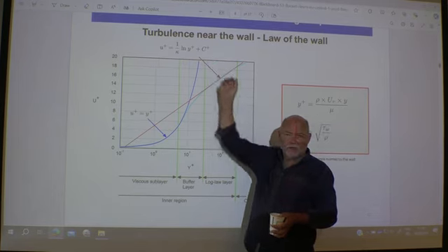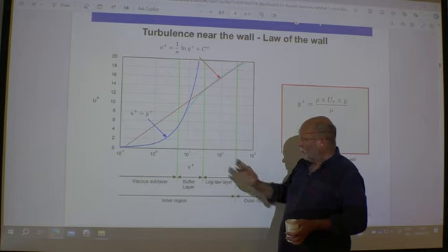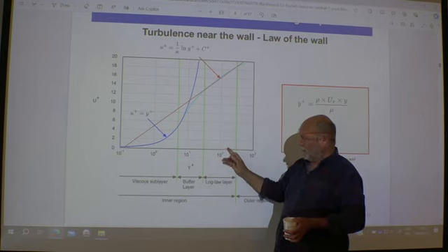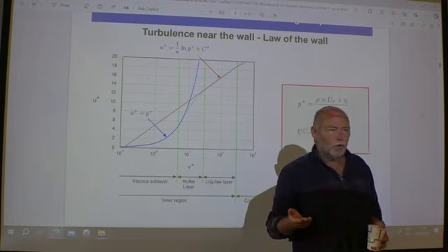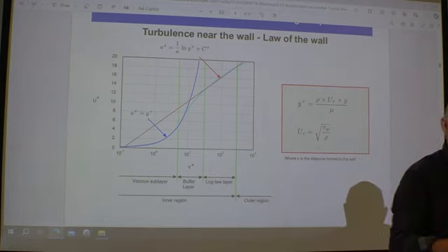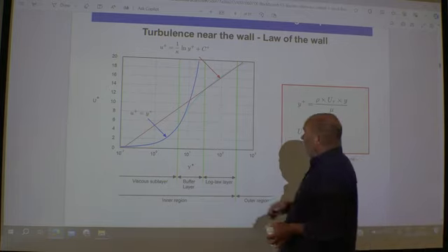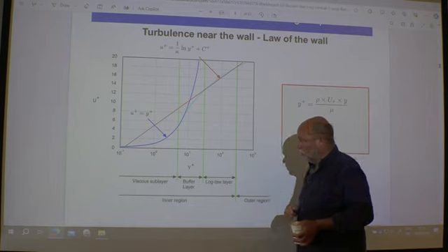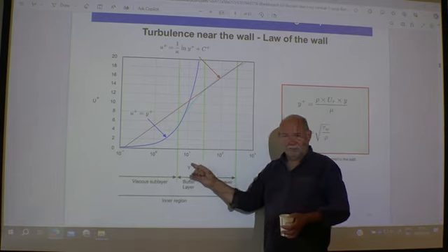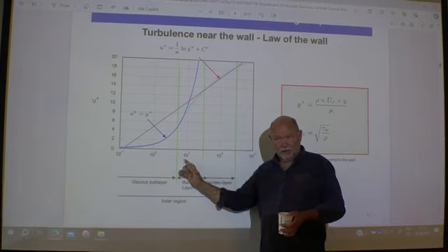Then we are going to need a wall function to describe the velocity close to the wall, because then we are actually jumping over a lot of physics very close to the wall. And if the Reynolds number is too high, you can't really describe it. You can't resolve the boundary layer very, very close to the wall. Then we have an option using this law of the wall. If you are in between, you're in trouble. So you should either be here or there, not in the middle.